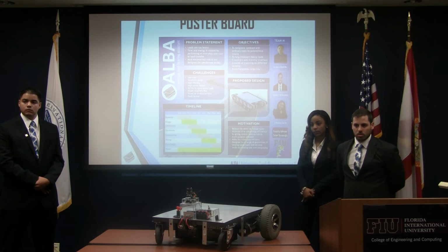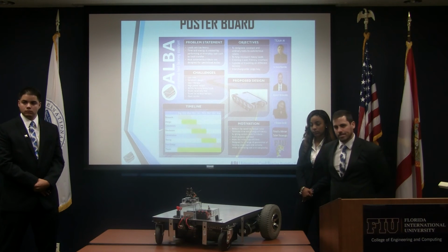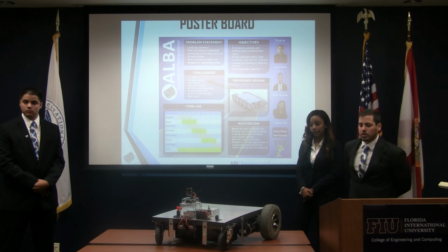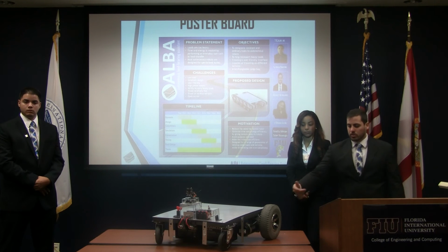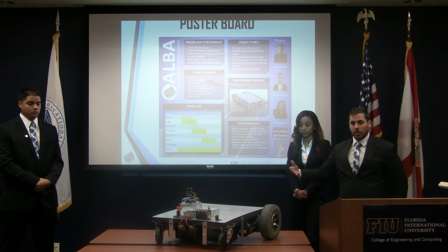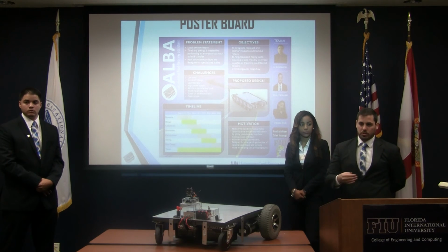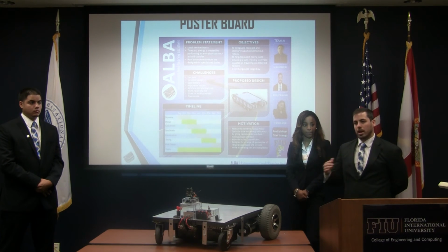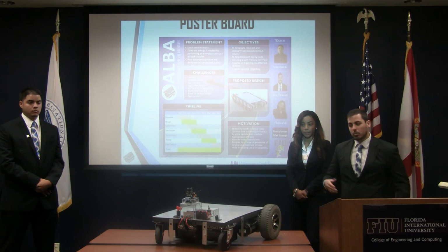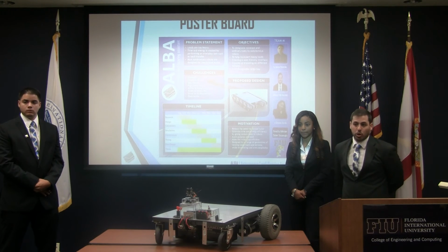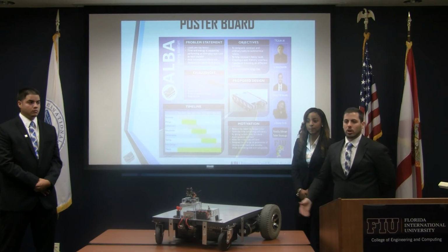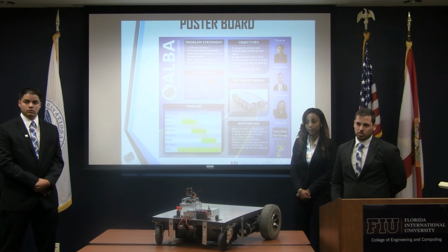I guess the main reason I'm asking is that you have 2 car batteries running this. Do you need 2 car batteries? You don't need to, but because we wanted big batteries, we wanted to weigh it down so it wouldn't spin out of control when it accelerated too fast, which it did at some points, especially when trying to stop. We also wanted a longer capacity so you can operate it the entire day. In reality, it only lasts about 4 hours at full speed. So you don't need car-sized batteries, but we like to have it run as long as it can and extend the life of the system.